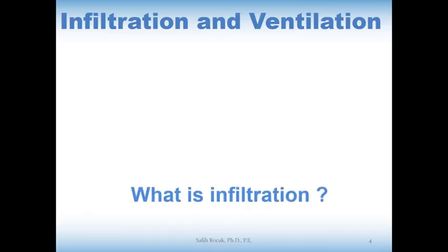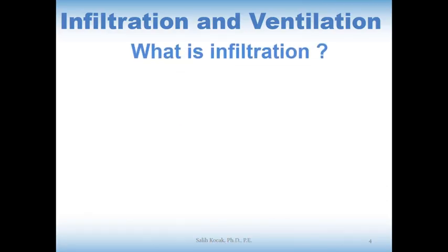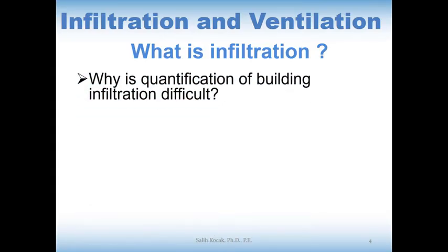And let us talk about what infiltration is. After making a little bit of sense of infiltration and ventilation, how they work, and why they are important, let's see what infiltration is. Infiltration is described as the air that enters a building through leaks. This is because of the construction quality, wind pressure, and also the temperature difference.